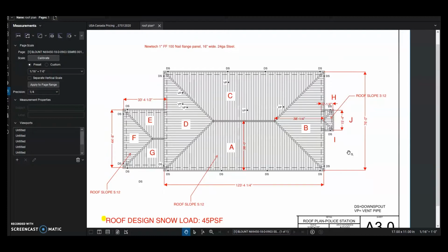If you measure down at 6 inches, then you have a 6-inch rise for a 12-inch run, which would make it a 6 on 12. You can also go to most good hardware stores, which will have a pitch indicator or slope indicator. Usually it's a little dial that you set on your roof and the needle swings to the right pitch.